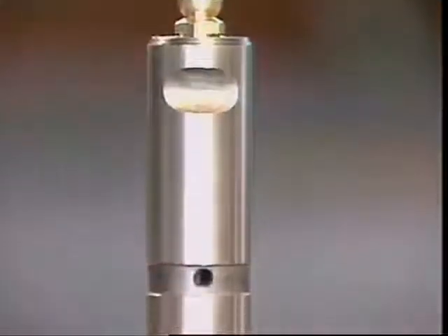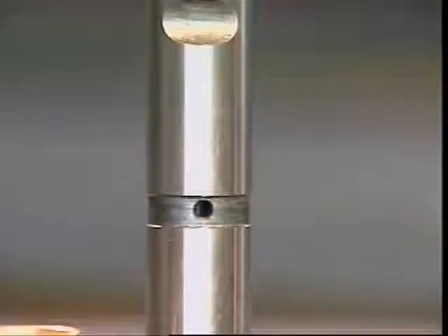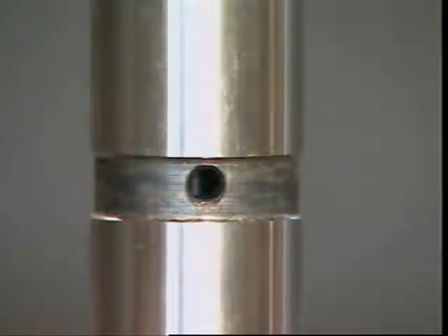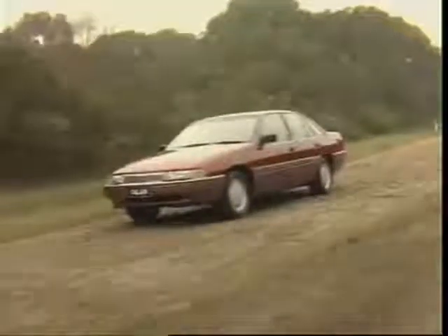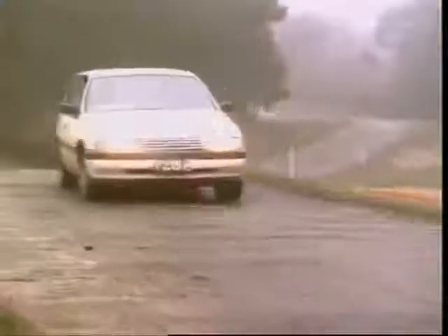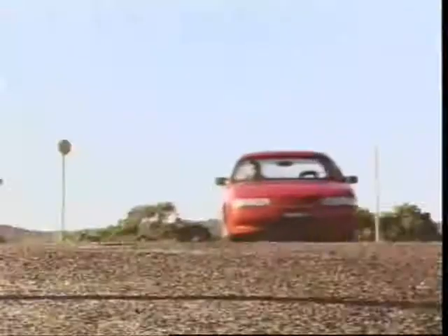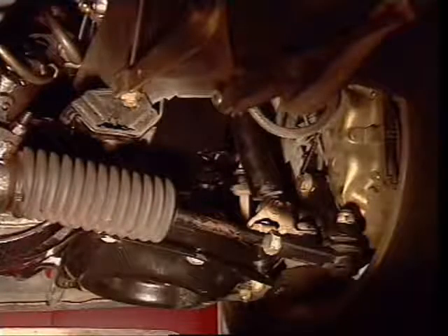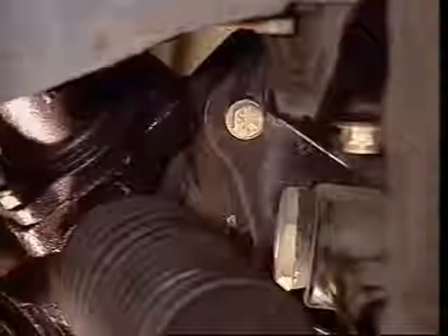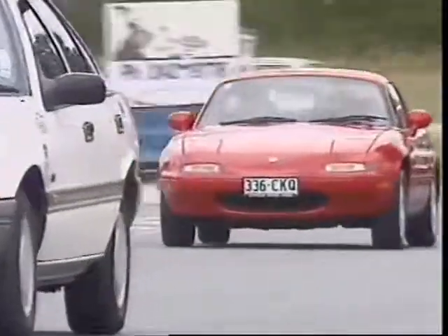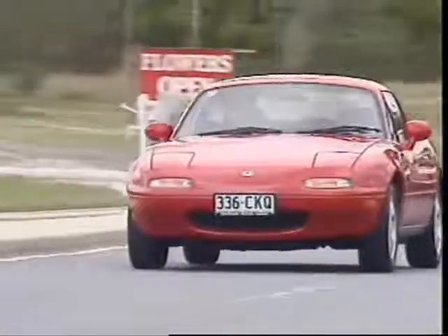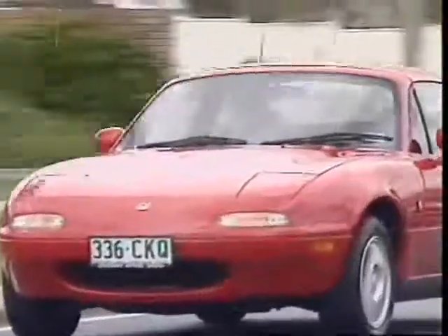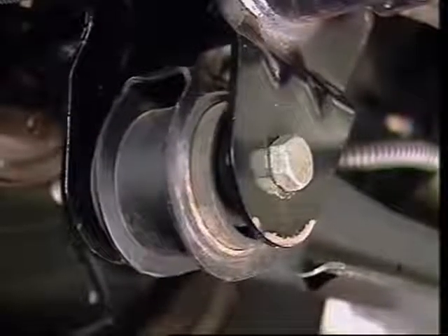The mounting pin on a metallic bush is usually drilled to allow for lubricating the bushes. Rubber bushes isolate noise and harshness and dampen unwanted vibrations. Rubber bonded bushes can be used to mount the steering rack to the vehicle frame. The rubber absorbs small impacts from the suspension action without transmitting them to the vehicle. Rubber requires no lubrication.